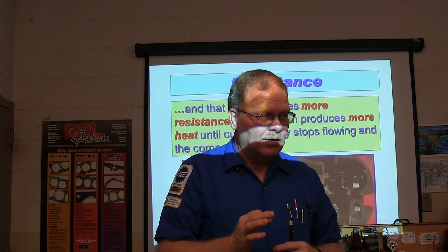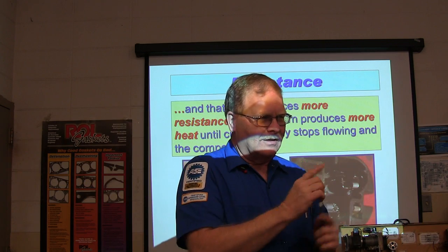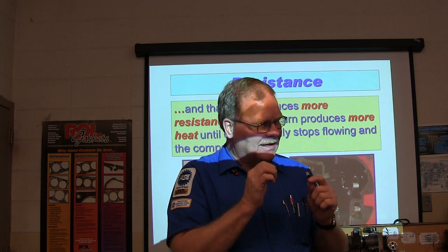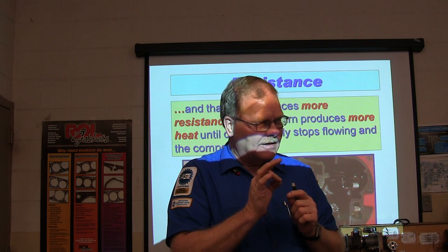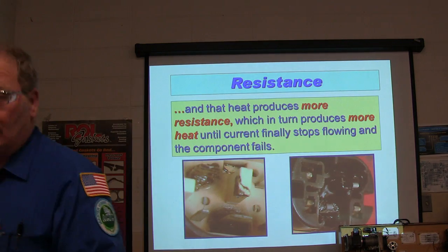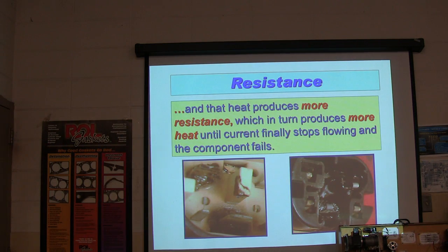Or if you can't get to it with your test light probe, you know those little stainless steel strips I get out of windshield wiper blades? You can usually poke one of those down in there and it won't hurt a thing, and it gives you a good test point. I always save those things because they're good for all kinds of stuff.